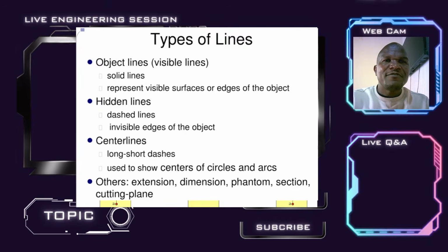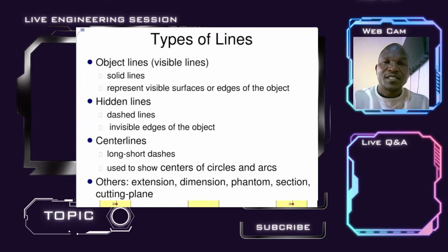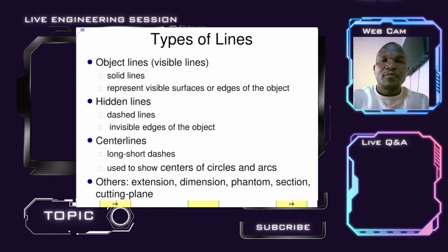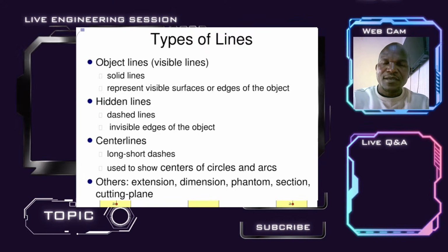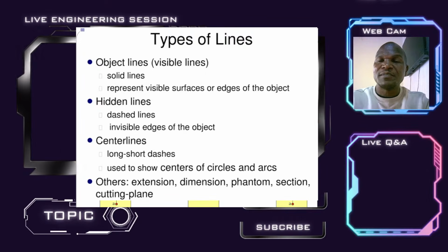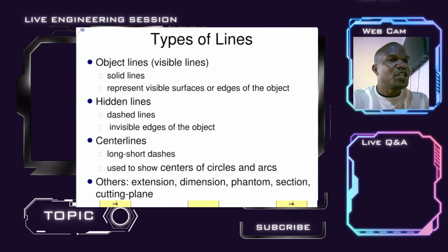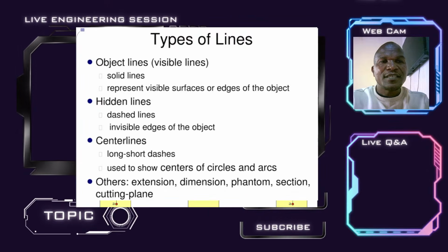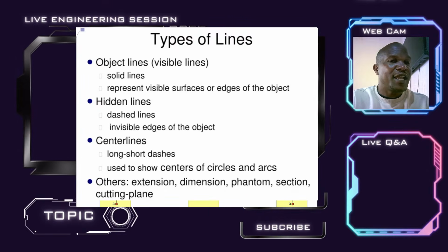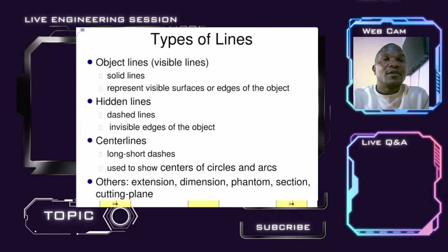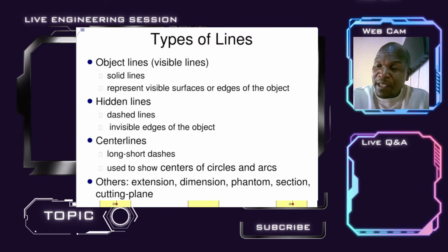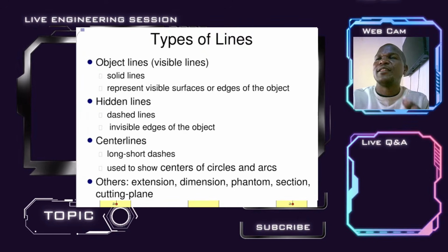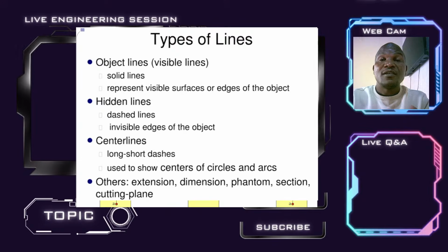Now, I have more than once talked about lines that are usually used. Not once, not twice, but I have talked about the precedence of lines. It's very, very important when drawing, especially here where beginners make mistakes. You don't get to differentiate between hidden lines, center lines, and other lines like the phantom line, sectioning line, cutting lines, and the solid lines. Why am I talking about this? Because once you miss that, the essence of engineering drawing and design is left out.